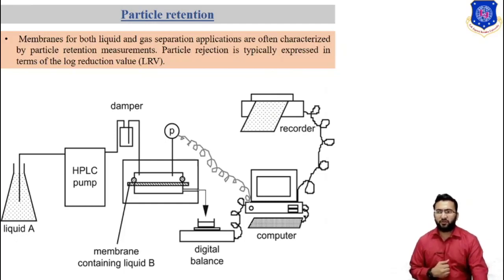Since there are many contributions to particle rejection, the filter performance can change with time, loading and particle distribution. For instance, under some circumstances, breakthrough occurs, such as a loss of rejection after a period of time. This can be due to the blockage of smaller voids. It is also true that the majority of convective flow through a filter is carried by the large pores.